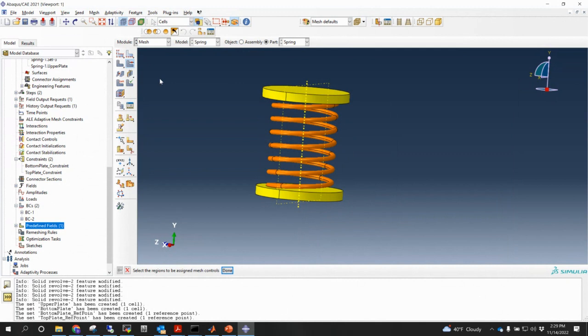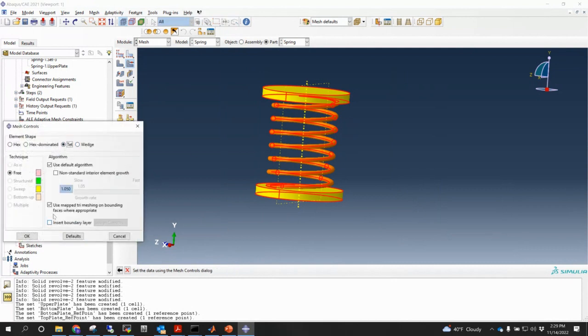If you're doing fracture, it has to be hexahedral elements. So it depends on the usage. For this, I'm gonna call them bomb-proof simulations that we are doing. Let's use TET. Tetrahedral meshes anything. It's surprisingly good, and it works.